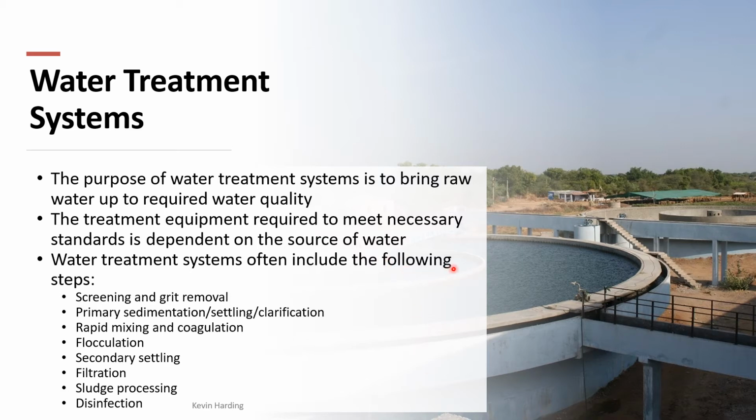As this flows in, water will flow over this top section here. There might be an initial amount of solids coming over here as well, so there will be a second opportunity for solids to settle out again. Again, they're going through the bottom, and you can see on the edge here, the water is trickling over the top as a primary settling tank, or this actually might be a secondary one. The water looks fairly clean. Okay, so that is a primary settling tank for clarification.